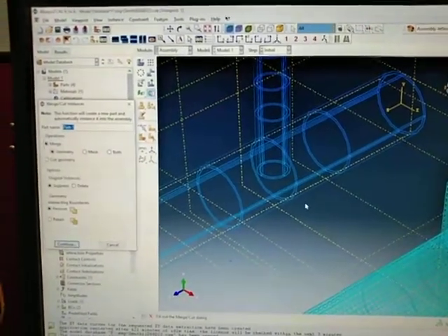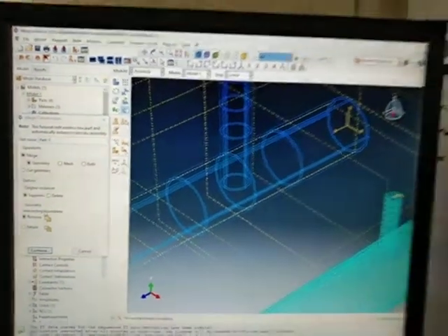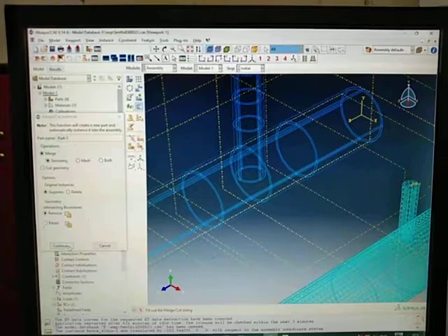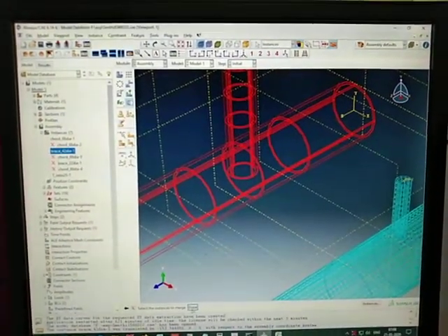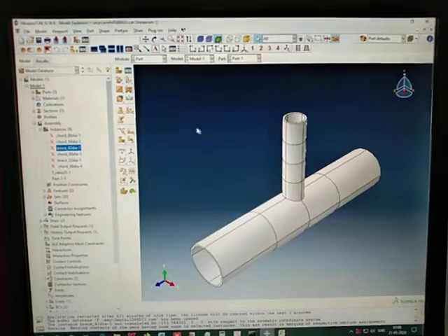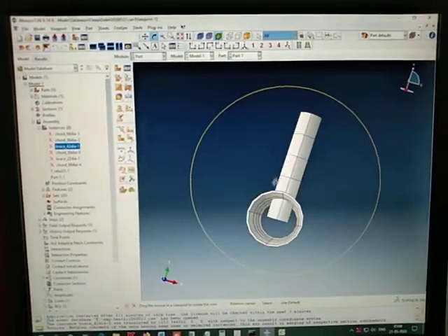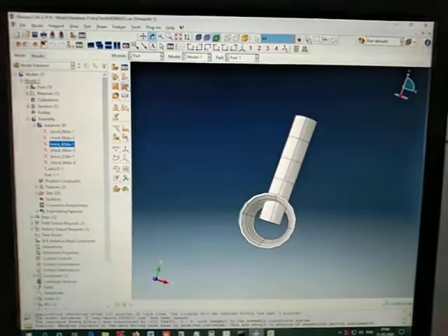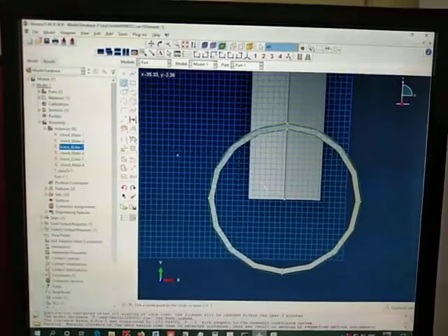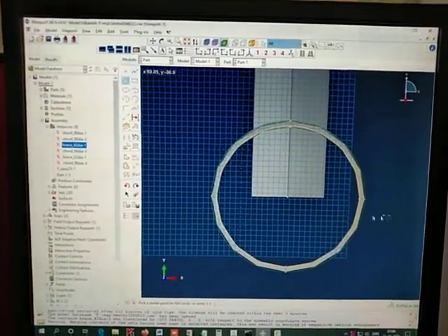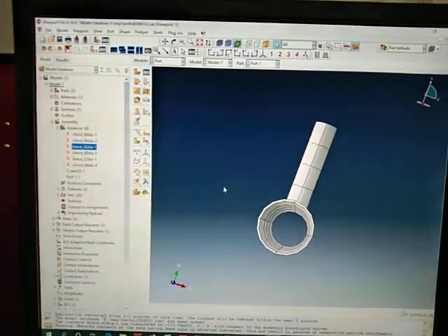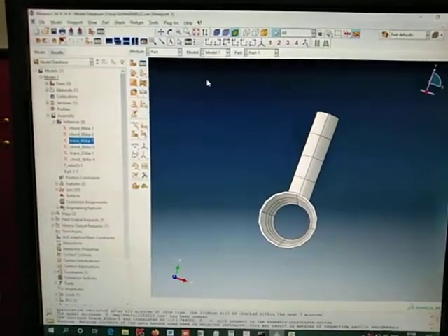Once it has been positioned, we can merge these parts. Here it will ask to remove or retain the mesh geometry. We need to have all these things removed. So these two members are selected. Now a new member is being generated. This is part 1. Now the additional part of the brace will be below, which needs to be cut using solid extrude. It can be chosen with the existing shapes as that of sketching the shapes in the part, which will completely remove it throughout the chord. So now we have a perfectly matched brace chord joint.